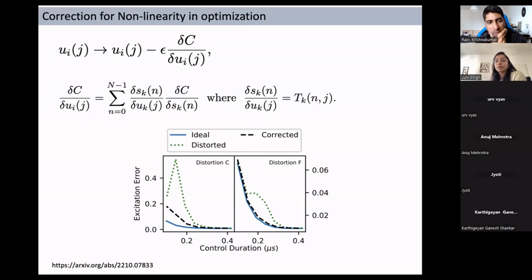You could also do it without using this open loop approach. As I said, if you didn't know what your AOM was doing, you could have just applied this closed loop thing. Don't care about whatever is happening, get an error, get the feedback, do it again. But in that case, if you want to change really small things, you're not able to do it because now it becomes a black box. You can't control and you can't know the things which are happening inside that.